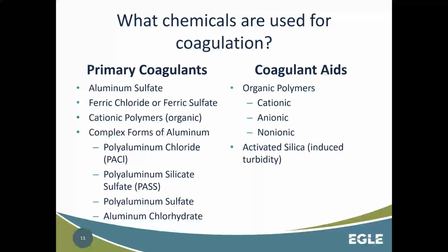Yeah. So as far as the coagulant aids go, a good example that I've personally heard is we had an operator at a Great Lakes plant, but the intake was located near a series of, I think, 5 rivers that all came into Lake Michigan in one pretty small area. So even though it was a Lake Michigan plant, the water quality was really dictated seasonally by the rivers feeding the lake. They had a lot of swamps, a lot of cedar, a lot of trees that produce tannins. When it's spring runoff, you get a lot of color in the water, and it wasn't being addressed by their primary coagulant.